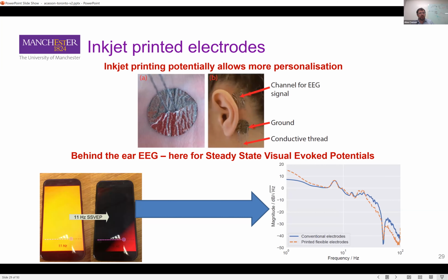In my lab, we've done that a couple of different ways. One way is by inkjet printing. In many ways, this is very similar to an inkjet printer that you might have, but now we're using conductive inks. Again, it's either a silver or silver chloride. I said I'd check that. This is a silver one, onto a temperature tattoo based substrate.